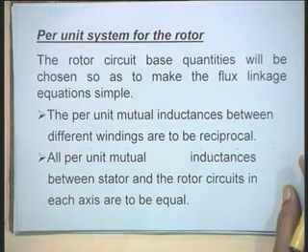When I write between field winding and stator winding, it can be written as LFDA. We want to make these two inductances equal, that is the meaning of reciprocal. Okay. Another thing which we would do to simplify the equations is that the mutual inductances between stator and rotor circuits on each axis are to be equal.